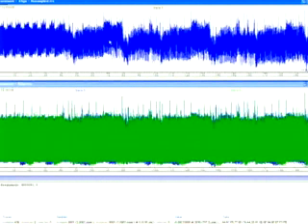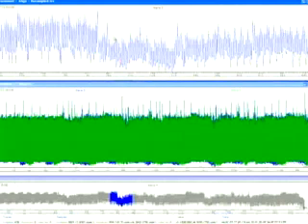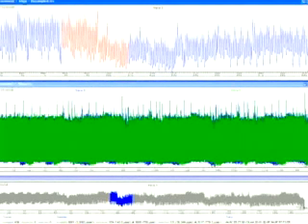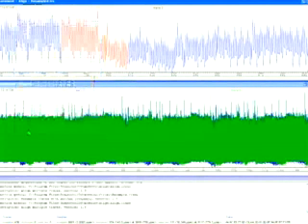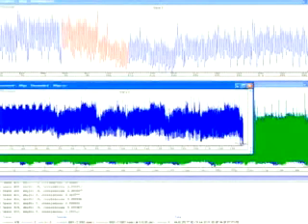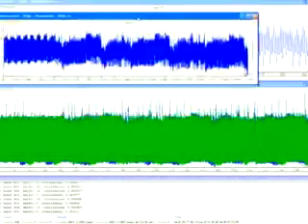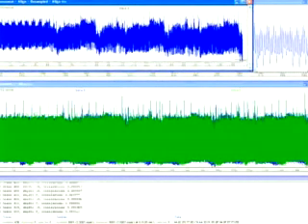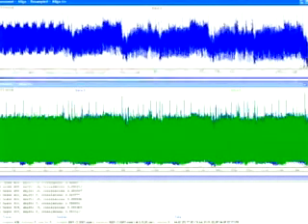So what we're now going to do is first make sure that this, again, is properly aligned, because the clock cycle alignment was not sufficient to align them all. You'll see there's a slight difference between each one in the structure of where the S-box was calculated. So we just want to align all the S-boxes nicely on top of each other. That goes a lot faster because there's a lot less data now. And now we're ready to do the correlation.